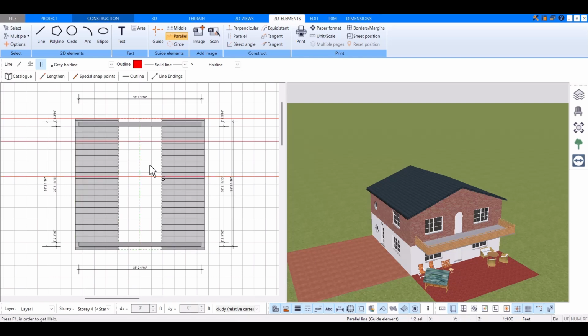Okay, I have now drawn two guidelines, one in the very center of the roof, and one along the top edge. Next, I'll draw some vertical guidelines, going from the bottom to the top. I'm going to draw these freehand, but I could also measure them, just like I did before. With this, I have drawn a rectangle where I want to draw in my dormer.